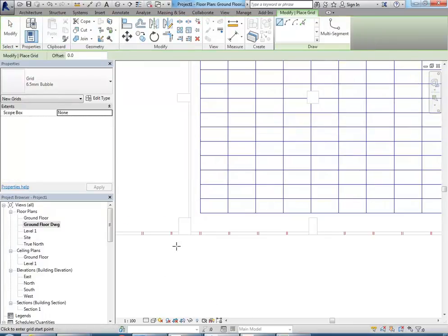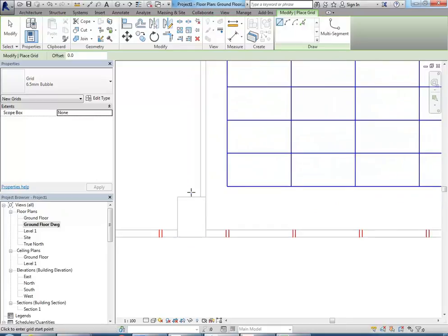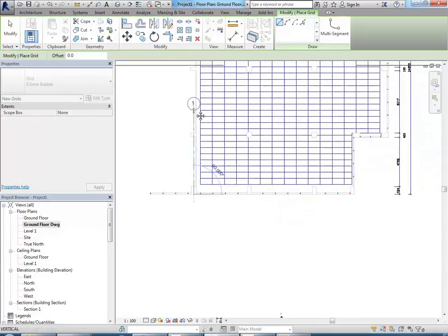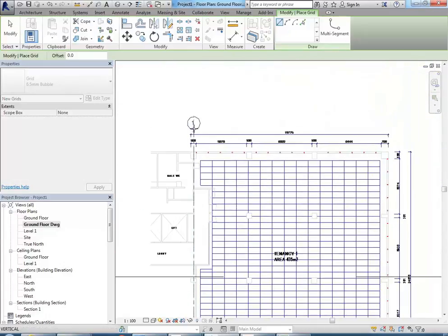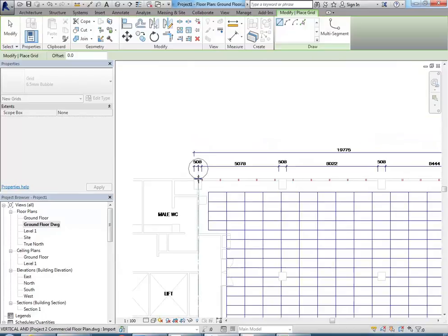and I'm going to zoom in and find a midpoint on one of the edges of these columns. We want the grids to be centered over the columns. So starting from the midpoint there, we'll center it. You're going to come up through all of these other columns, and you can see there it's going exactly through the midpoint of that column at the top.